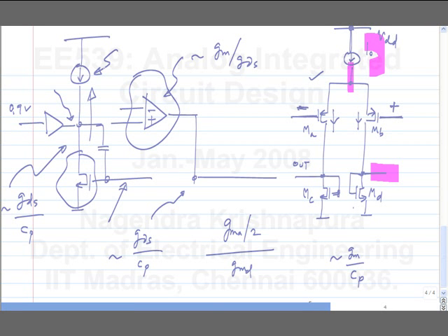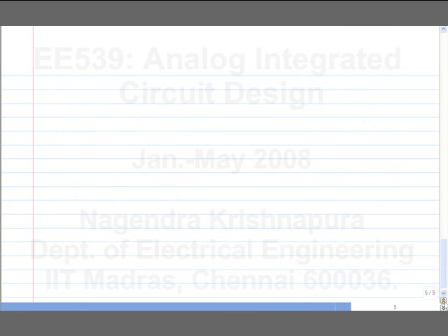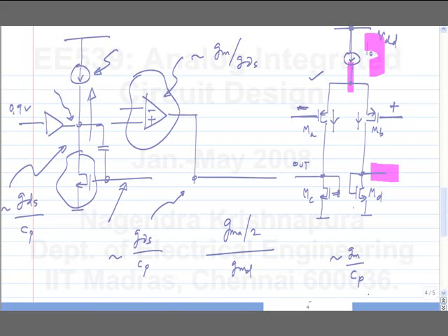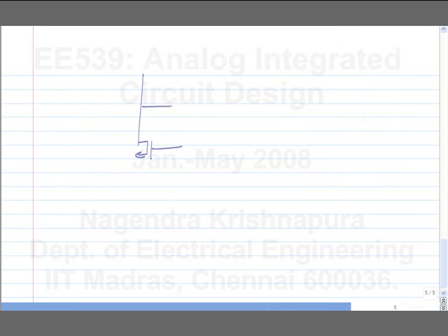Otherwise, you mean why doesn't it happen if you do the correct thing? Oh, he said instead of using a differential pair like this, he will make only an AC feedback path around the transistor and make sure that this is biased at 0.9 volts by forcing the drain through a buffer. Okay, but the replica doesn't work without DC negative feedback around here.